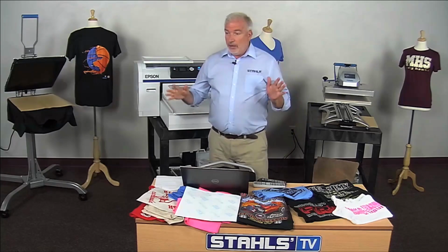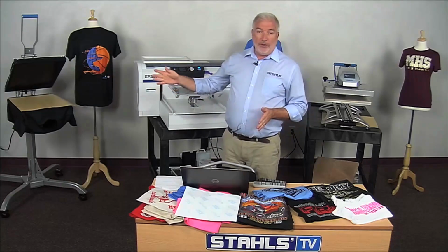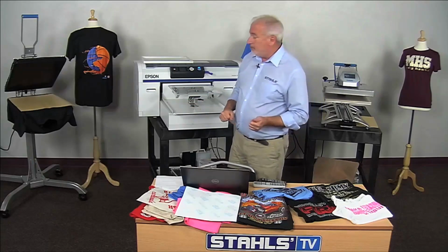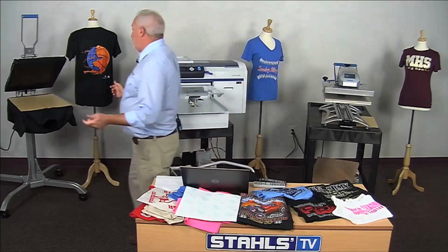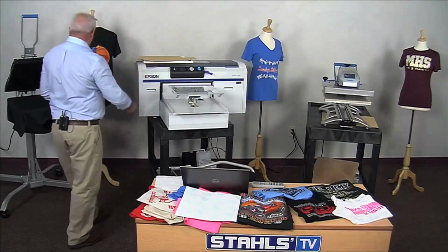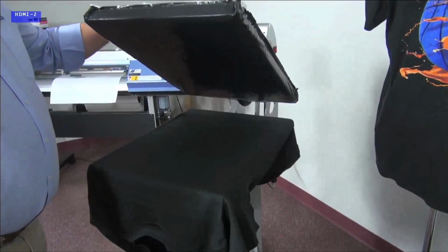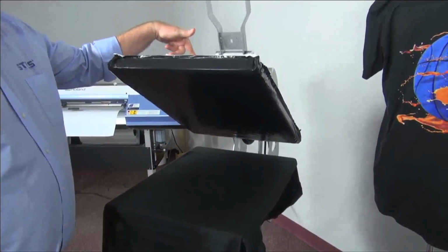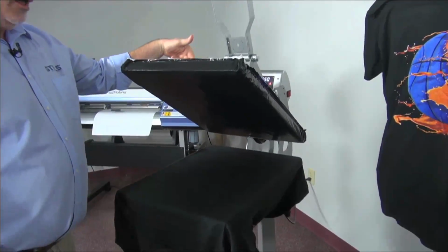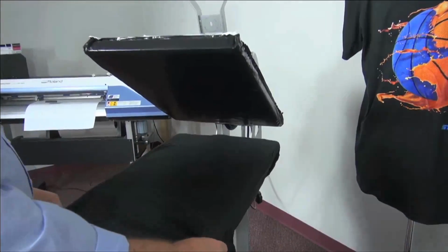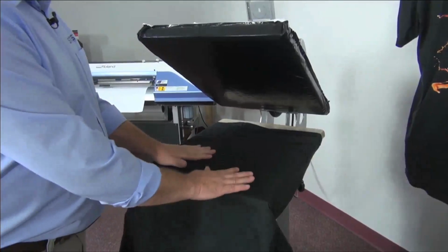All right, so let's look at the shirt that we're going to be working with. We're going to put it on the machine itself, and we're going to print a design. Now on the heat press we have here, this is the Hotronics Auto Open Press. I do like to use an auto open press because remember the dwell time on this process is about a minute or better at 350 degrees. So I don't really want to have to be here and wait for this thing to beep so I can come lift it off.